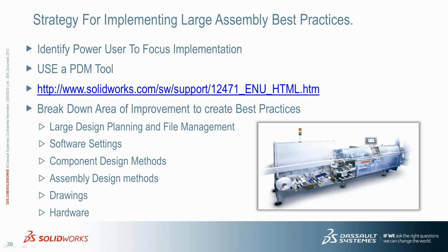99% of the time when you create drawings or you're just viewing the upper level assembly, you don't need to see that text. Now, if you do need to see that text in the assembly, create a configuration of the assembly so that that part isn't loaded with all the text all the time. So you can simplify it all the way up through the process.